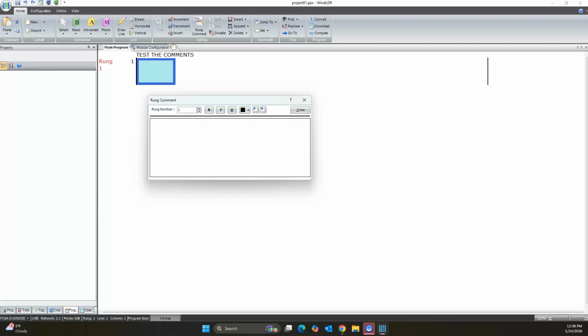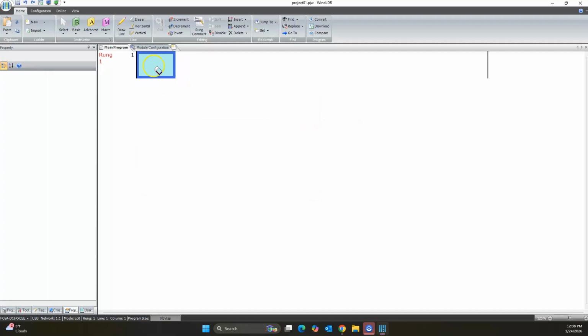what a rung does. So if I was going to make an instruction to control a pump motor, and it's my, fill in the blank, pump motor, whatever descriptor you want to apply to that, I would put that comment in for this just so that I know when I go back, oh, this is where the start and stop function for my pump control is, right? And I'd put that in my comment, start function for pump number 1, or whatever it is. So very, very good, very useful.